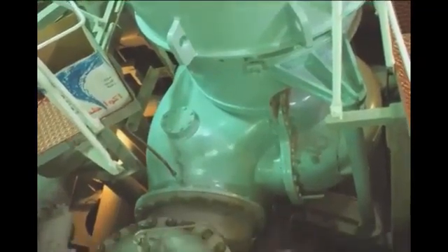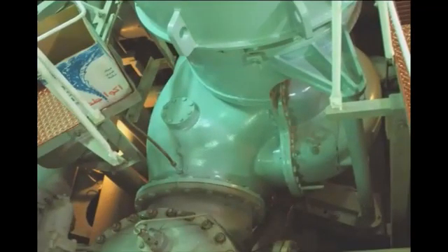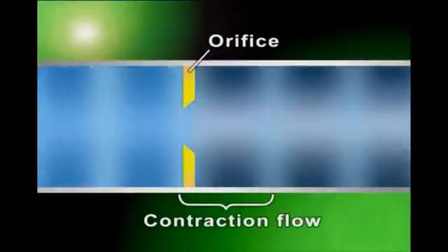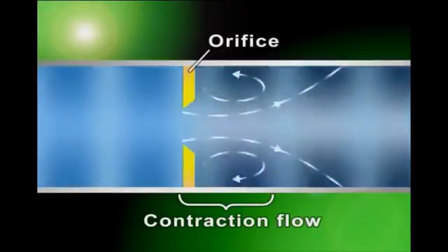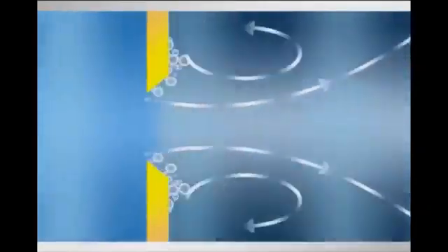Cavitation is one of several phenomena you should avoid when operating cargo pumps. When water flows fast through a region, the pressure falls below the water's vapor pressure, causing vapor bubbles to form. As they collect, these vapor bubbles create a cavity, a phenomenon known as cavitation. When these bubbles break, they produce minute vibrations that cause abrasion. Repetition of such vibrations leads to damage to parts of the pump.